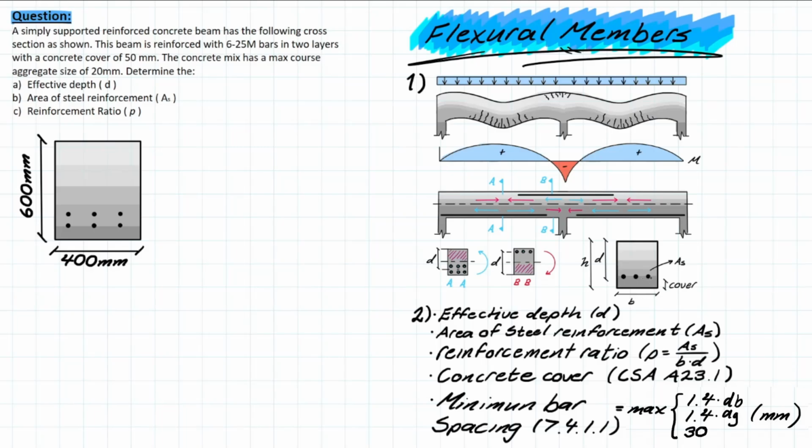And the further that distance is from your reinforcement based on this concrete cover, the more protected it is from those infiltrants. And in addition, if there is a fire in your structure, this cover will slow the damage that will occur to this metal element, right? So those are the two reasons why we have concrete cover.